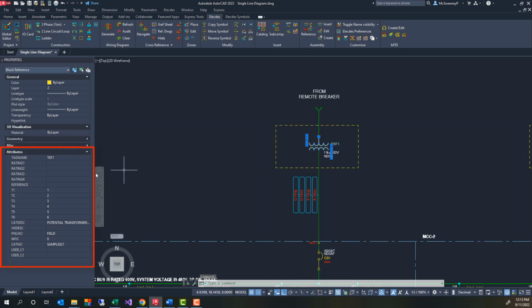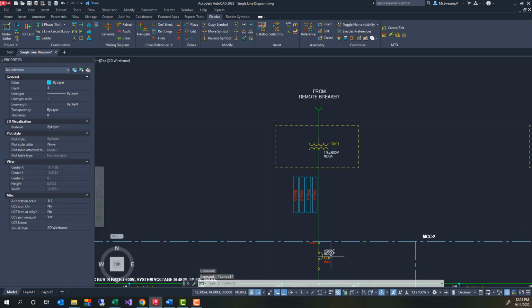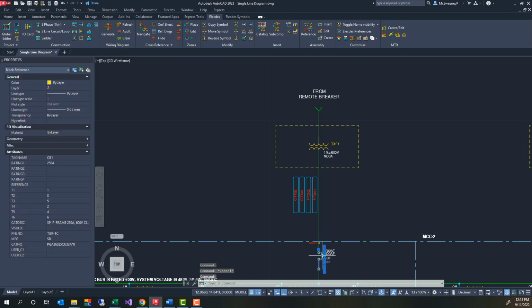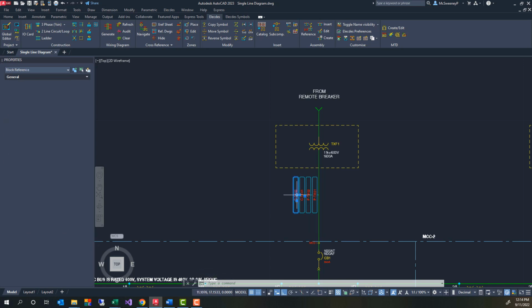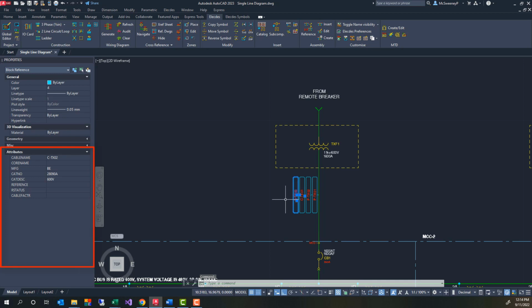Paneldes components contain attribute data, are smart and can analyse the connections of cables connected to them. In my case, I have a transformer connected to a breaker by 4 cables. The cable markers are also smart and contain attributes which identify the catalogue specification for each cable. The cables are stackable. This is faster than drawing in a line for every cable. Paneldes will automatically scan this diagram, ID the components, ID the lines connecting the components, and then capture the cables on those lines.